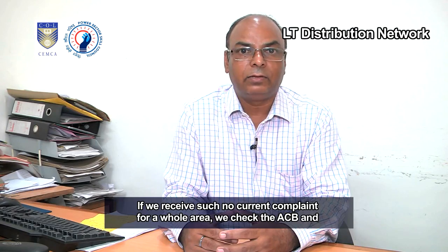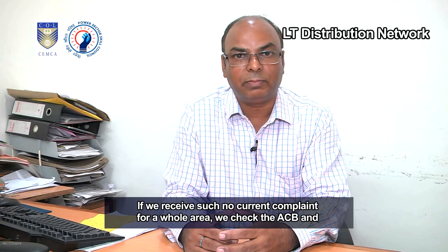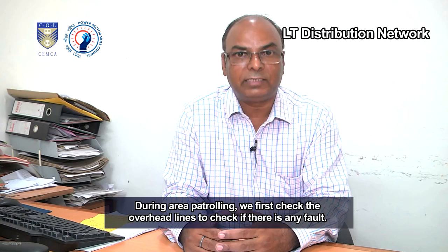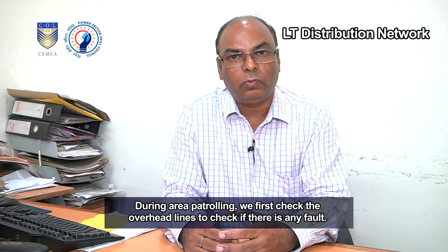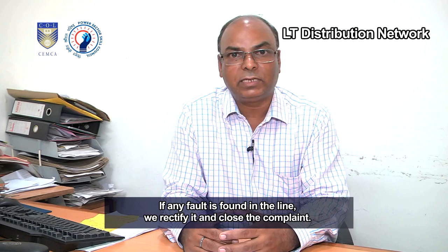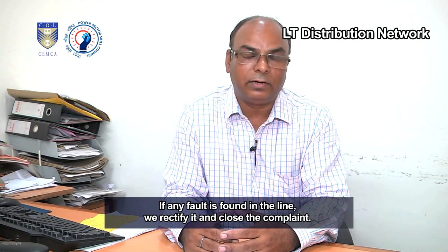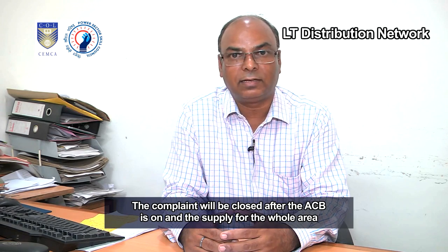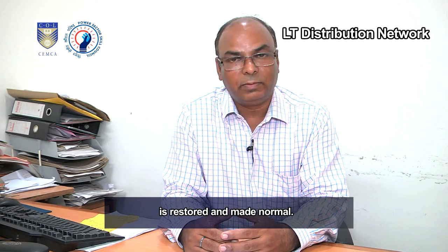If we receive such a no current complaint for a whole area, we check the ACB and then do area patrolling. During area patrolling, we first check the overhead lines to check if there is any fault. If any fault is found in the line, we rectify it and close the complaint. The complaint will be closed after the ACB is on and the supply for the whole area is restored and